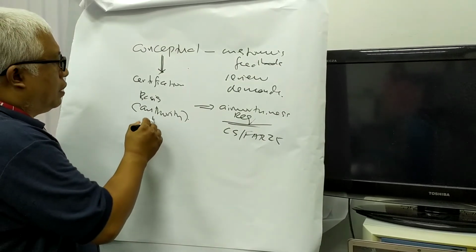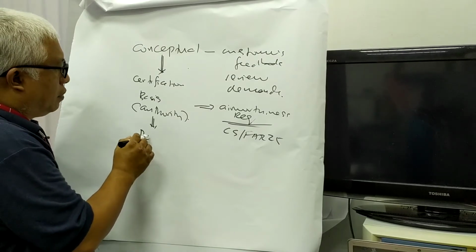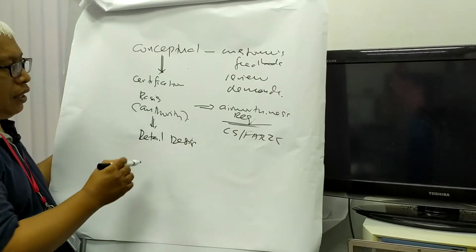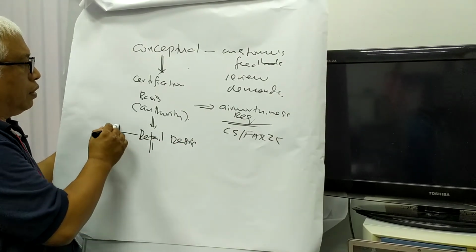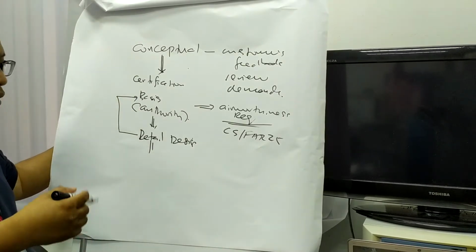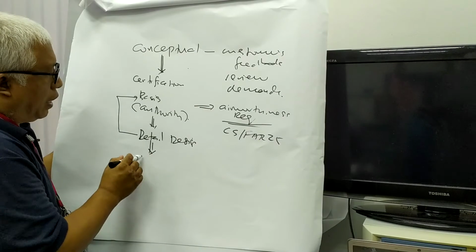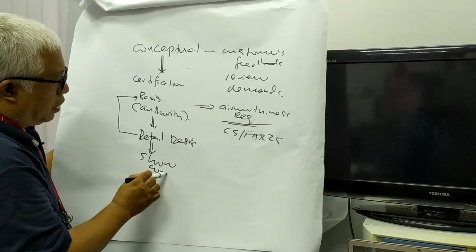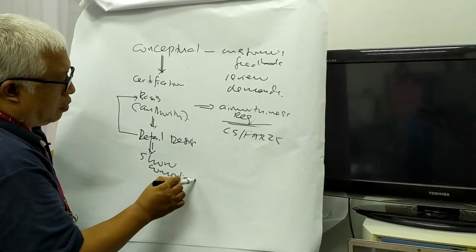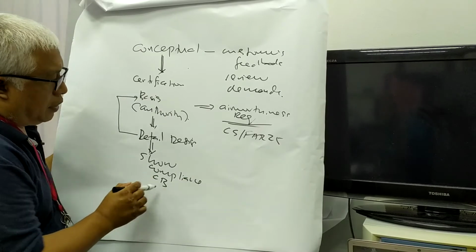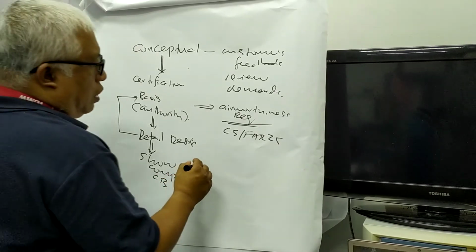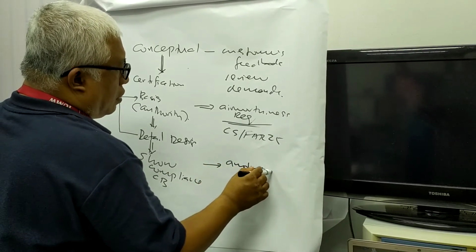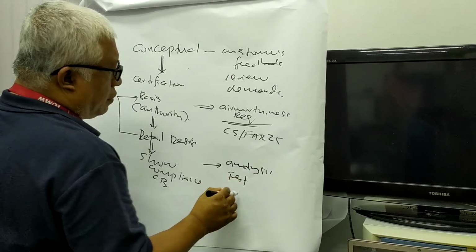Once we have the cert basis, then we go to detail design. In detail design, we should always refer back to the cert basis. Anything you do in detail design, you shall comply with the cert basis. So you have to show compliance to the certification basis. During the show compliance process, you may do analysis or you may do test.